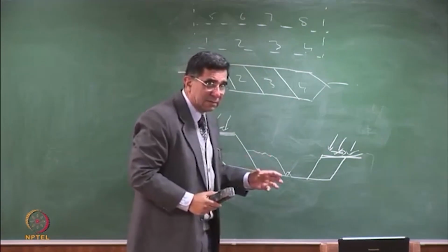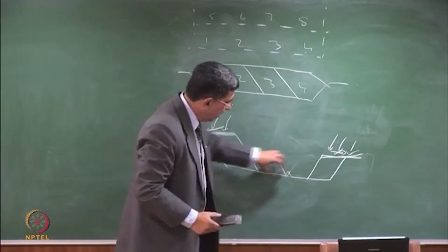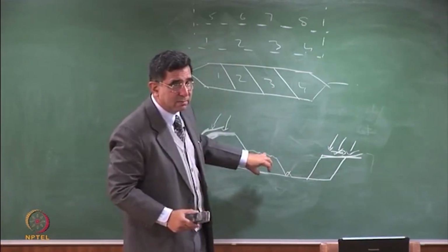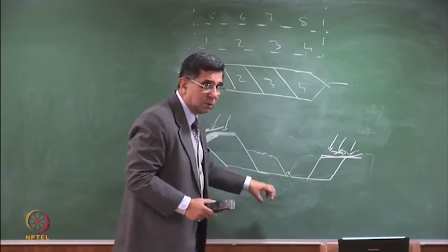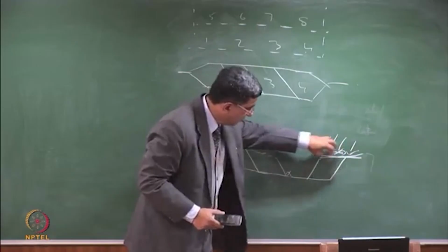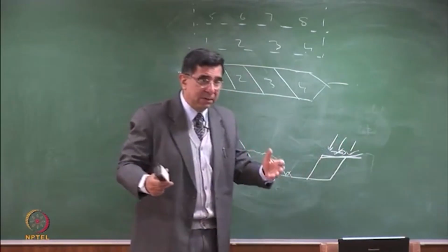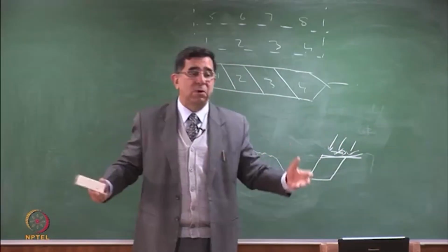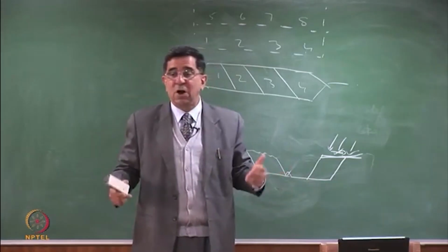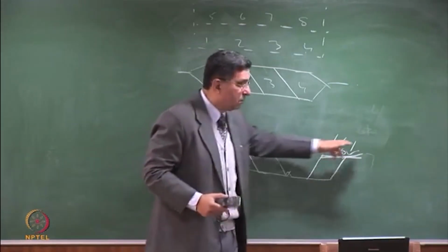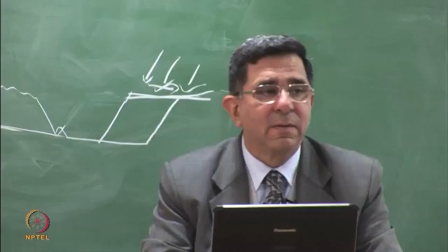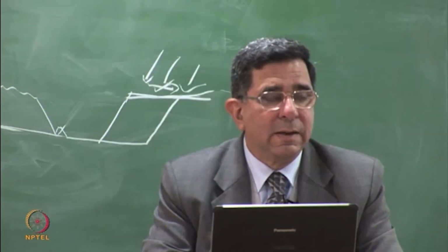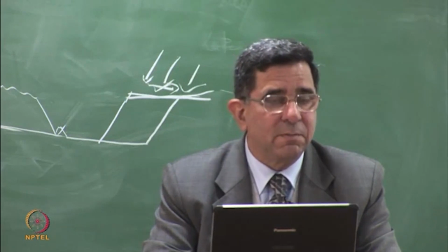The problem is that if we operate like this, and if this water also starts to come here, then you have a lot of leachate, not only from the precipitation falling from the top, but also from this. And if this is sloping inside, and I have seen this happen, below ground landfills actually becoming ponds, because not enough precaution was taken to keep the water out. Any questions? Keep excavations to a minimum.